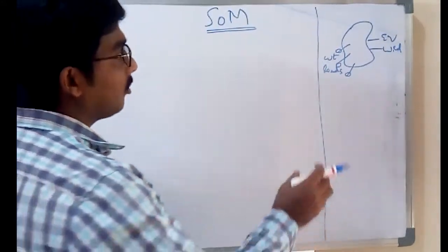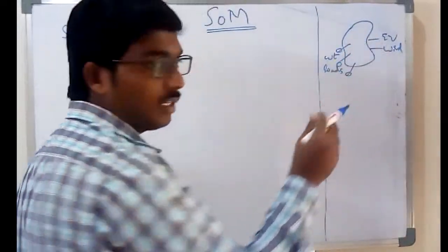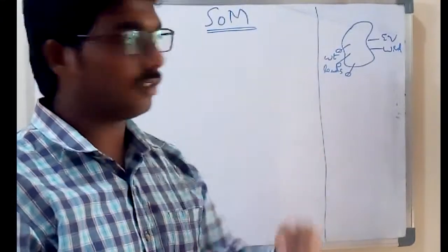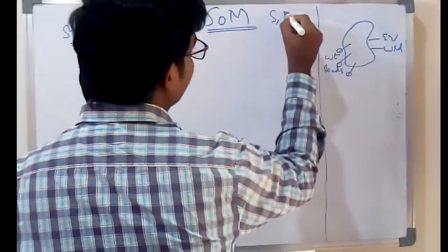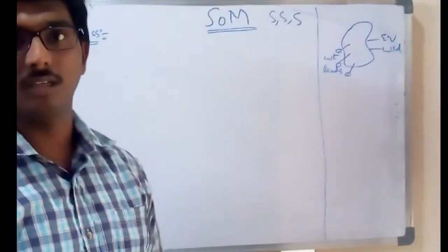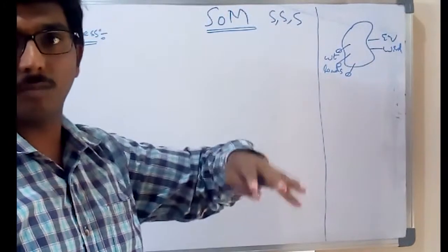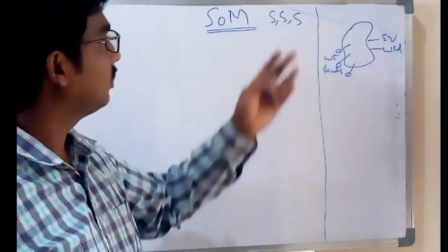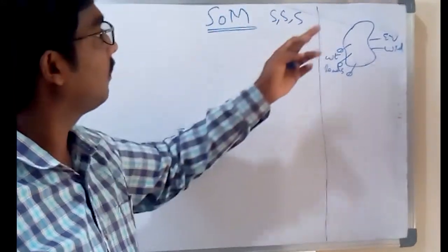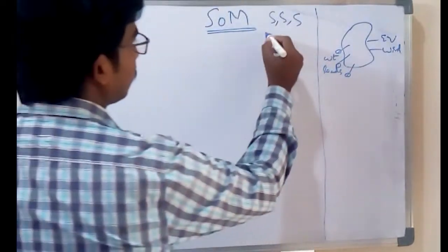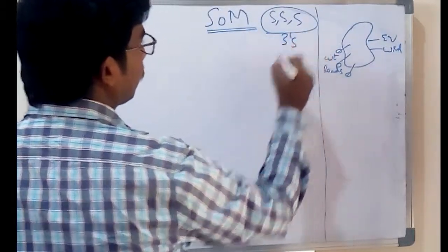In strength of materials we study whether all the deformable elements can withstand the load they are getting. Mainly three S's are dealt with: strength, stiffness, and stability. Strength is whether it can withstand that much load or not. Stiffness means there will not be much deformation; it is load per unit deflection. Stability means it will not deform due to the loads. These three S's we study in strength of materials.